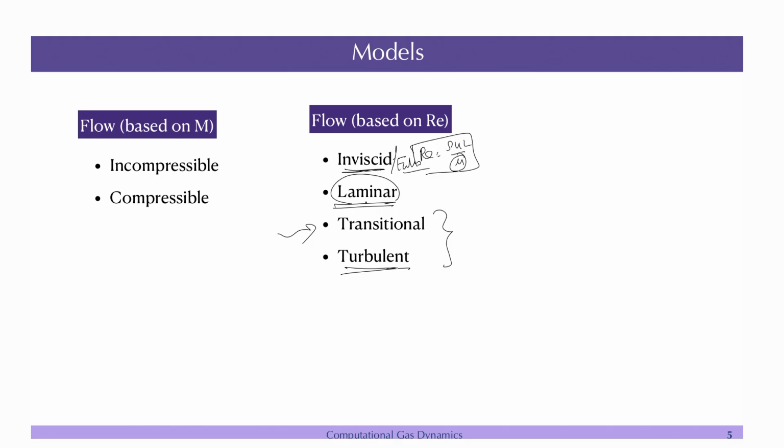Because laminar flow will lead to the boundary layer, and then you have shocks which are coming because of the high Mach number, and they will interact with one another. And that will lead to separation, the shock strength will change, and so many things. So it is by itself a complicated problem, and then we are talking about turbulent flow.